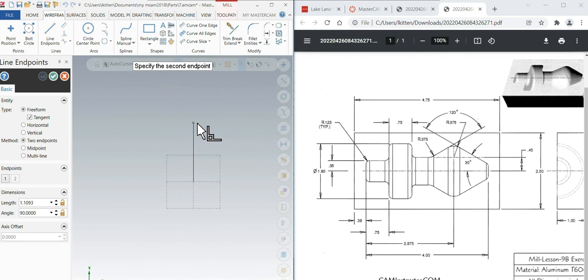So hit the space bar, and that brings up the quick entry, okay? So now you're basically typing X, Y absolute points. Okay, so we started out right here, this little point here. And we're going to go straight, ignore all the radiuses for now. We're going to put all those fillets in later. We're going to draw a line up, over, down, over. Then we'll put the circle in here. We'll draw a line tangent at like 30 degrees negative and 30 degrees positive. We'll set a line over, and then we'll be done.